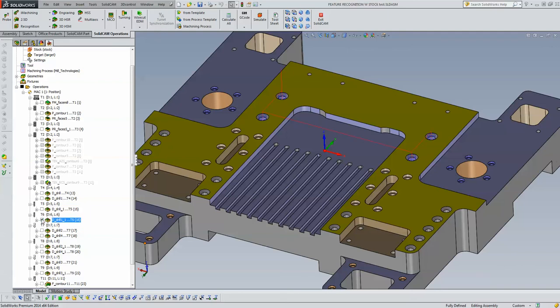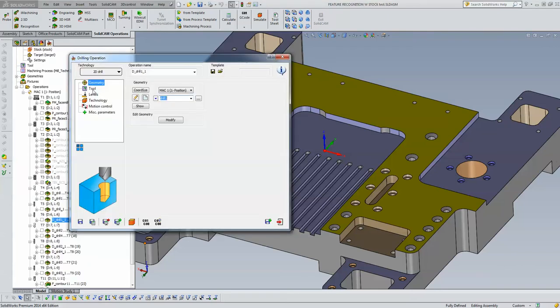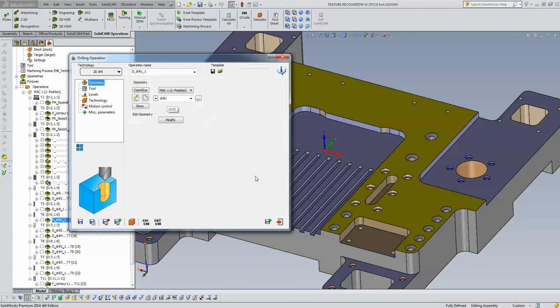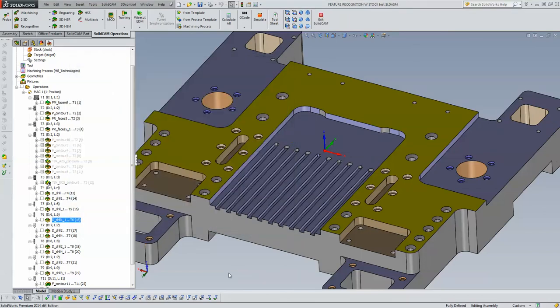This one is a larger hole over here, so we're going to use a different drill, which is perfectly okay. Again, making sure I switch geometries over there. No problem, I did that as well. Okay, now next, I wanted to drill work on these holes over here. Well, for that, again, I did a spot drill. And note, this is the same diameter hole, but I can't do the same operation for this one as well as this one because they're on different depths.